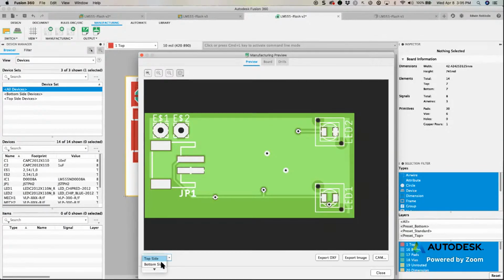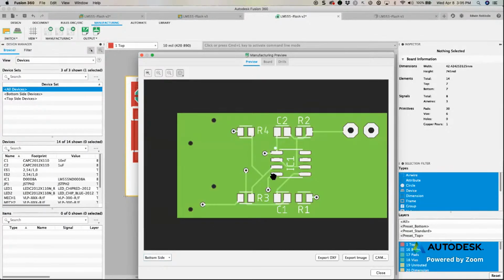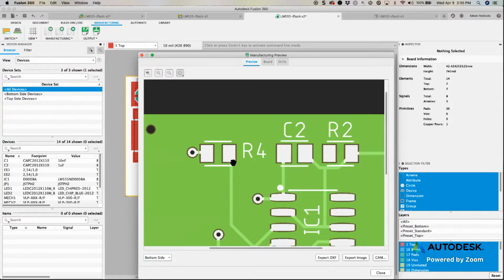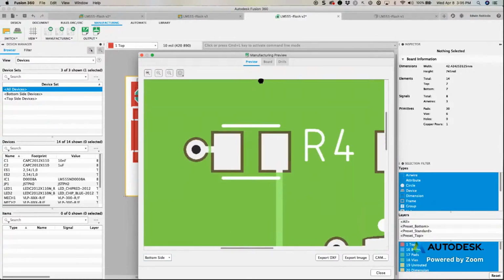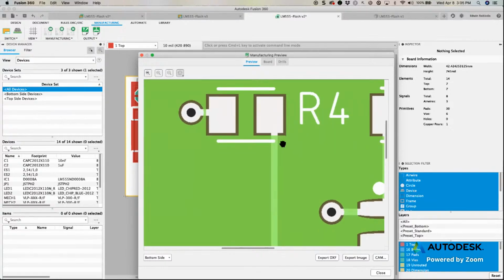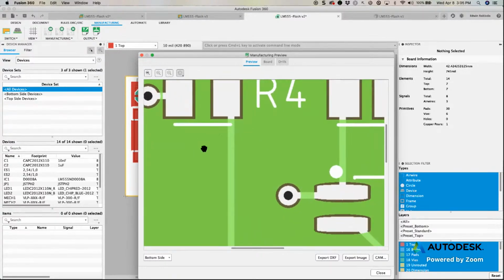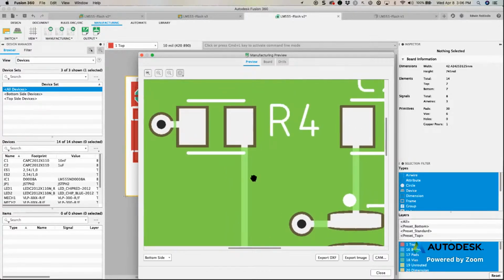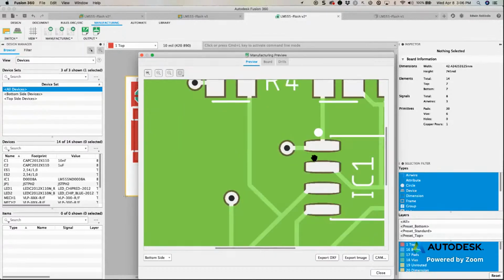Flip it around. Let's take a look at the bottom. I think there's more traces on the bottom, as you could see. So here, I'm going to use this one as an example. This green material is that film, the solder mask, the film that they put over the board to protect all your traces. Now, your components are actually exposed. They're landings, not the components, the landings. In other words, the soldering points are actually exposed. That way you could solder your point.